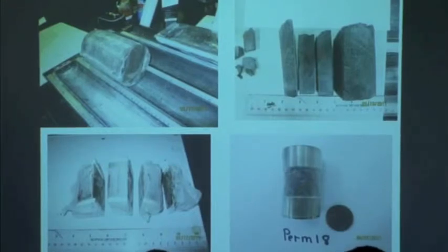So here, in one of the times that I went to sample, we've sliced up the core, and the better parts of the core, you can make decent slices like this of it. Other parts of the core, especially the bands that are deforming more, are very crumbly, and it's very difficult material to work with, but we did our best, and you can end up with samples like this that would be a sample that we would test resistivity and permeability on. So these would be undisturbed or whole, undisturbed core samples.